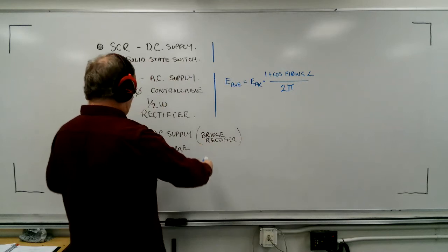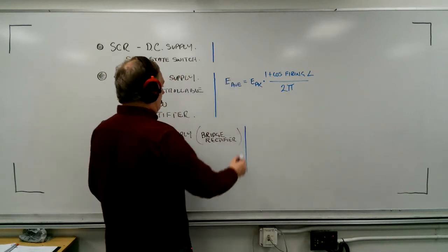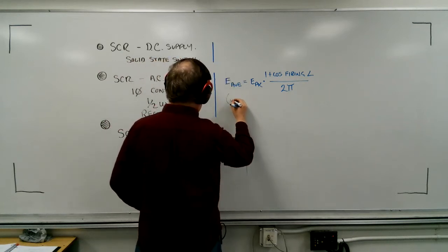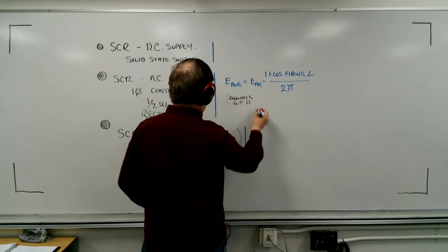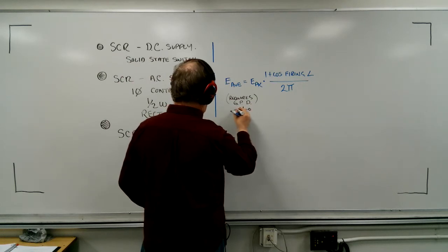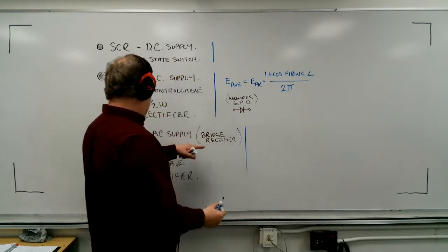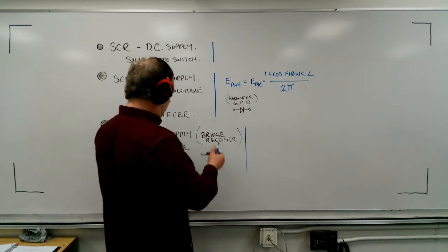Then we moved on to the full wave. The other little note that I'll make, because it was a little different between the two, was this one requires a gate protection diode, okay? Now this one here, remember we fed through a bridge, so that means it was actually DC going into the SCR.